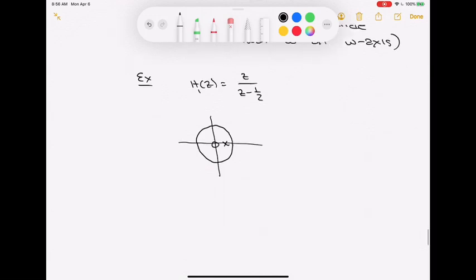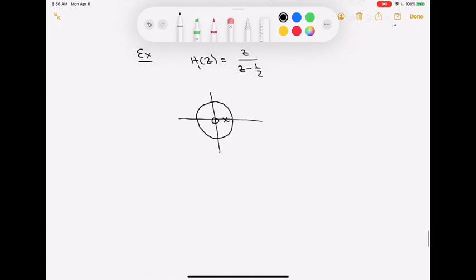So I'm going to start out with the magnitude response. If I wanted to take a look at that magnitude response, I'm going to go ahead and just draw a quick axis here. Unlike continuous, where you have to maybe spend a little more time thinking, what frequency range do I need to go over? It's always the same in discrete time. You're just going to go over that principal range, because if you cover that, you know everything, because magnitude and phase response, frequency response, is a 2π periodic function. I only need to get enough points to be able to sketch it over minus π to π.